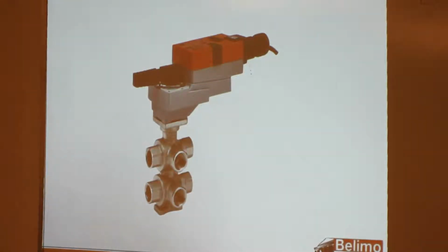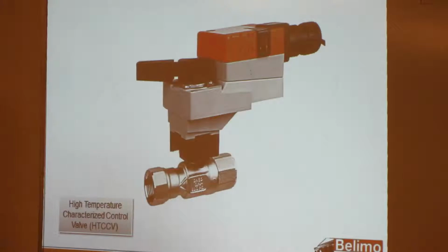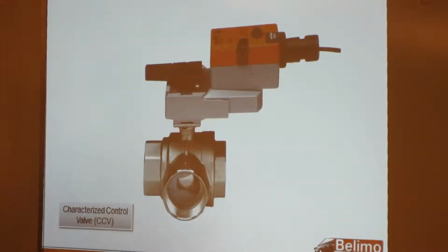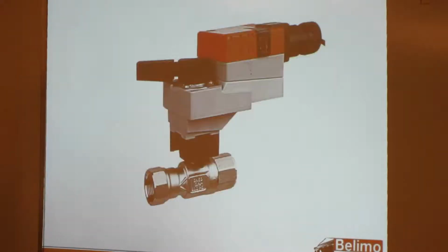How about the disc, how about the orifice? This disc here gives the equal percentage characteristic to it. So it gives it a nice characteristic. Yeah, so we'll see in a few minutes, there's a slide that'll show characteristics of a coil versus characteristics of a modulating valve.